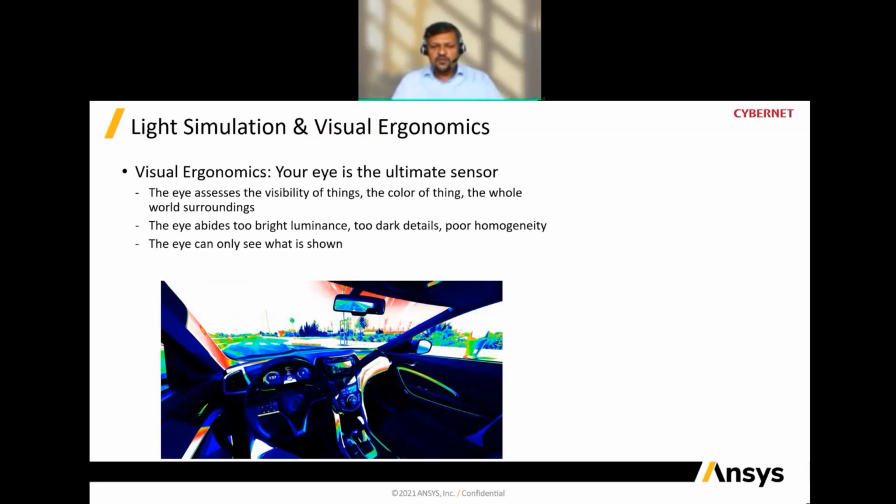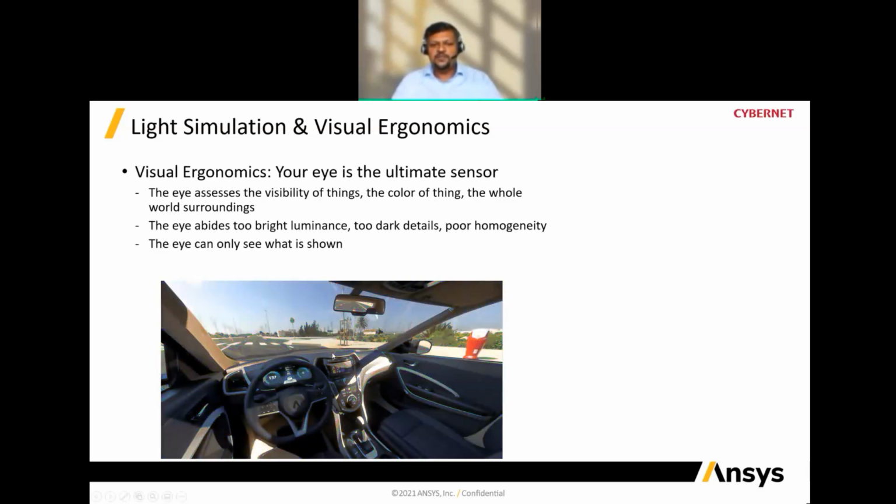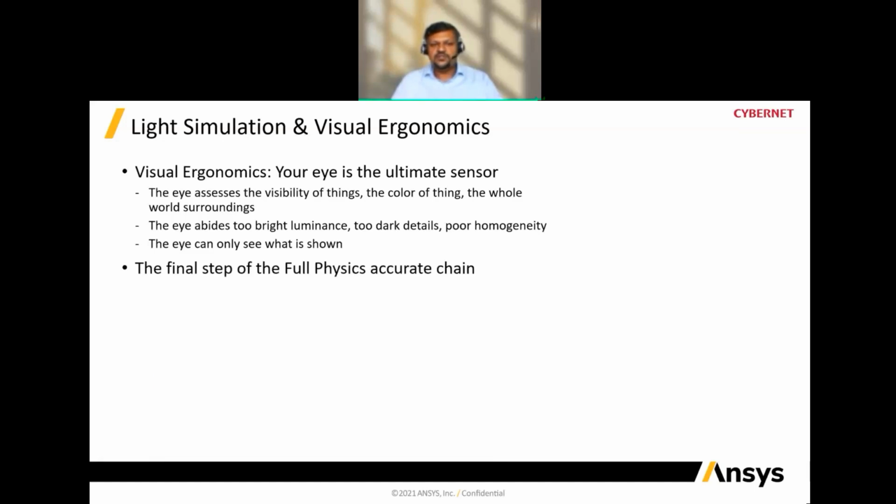It's not only a photo we are looking at, but we are also doing a simulation virtually to see how the light distribution is happening. Where are my hot spots where light is more accumulated, or where are the dark spots where we have less light? We can see in different color plots, and then also study if it is going to create a washout or a reflection or a glare. So we can study those kinds of things.